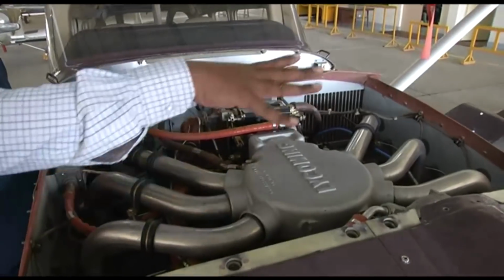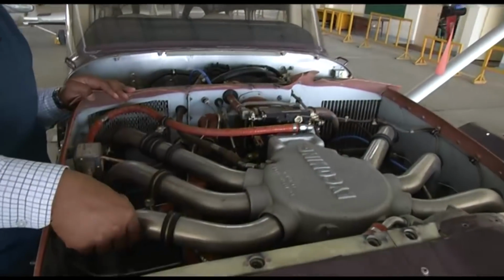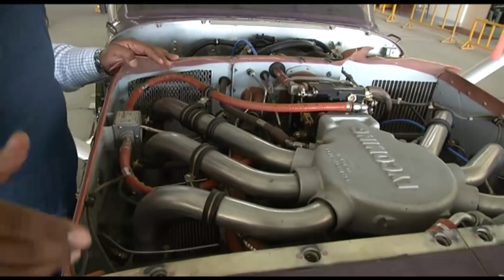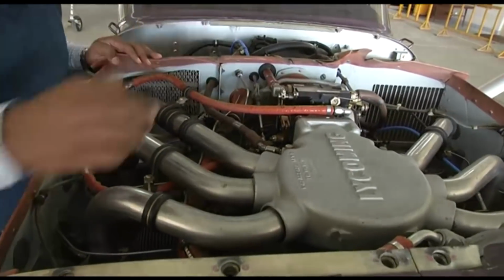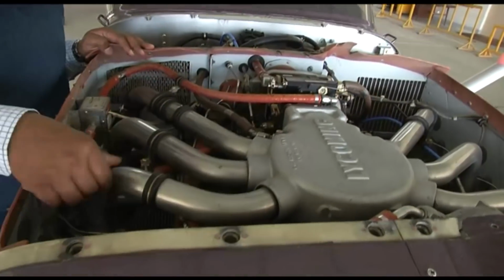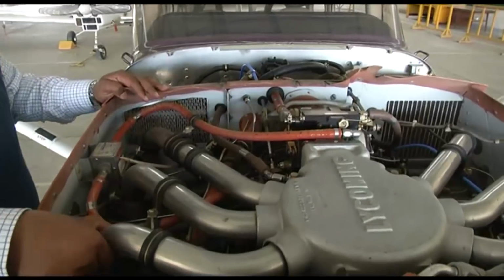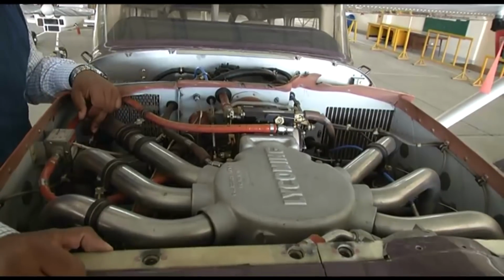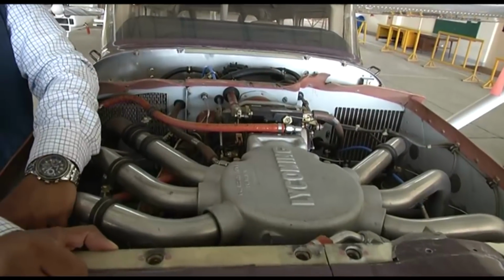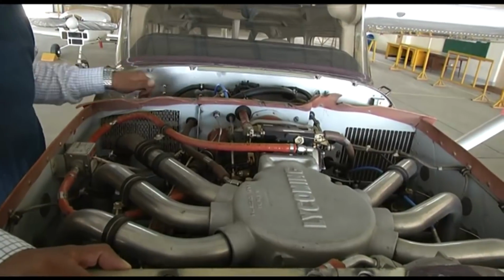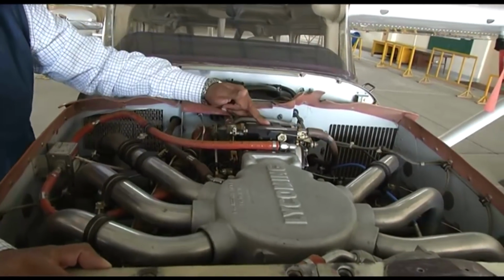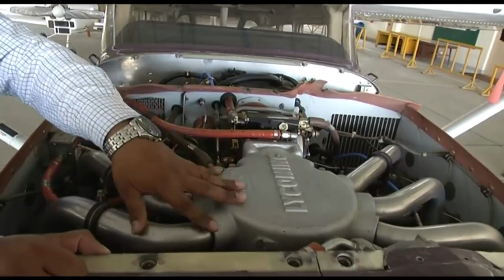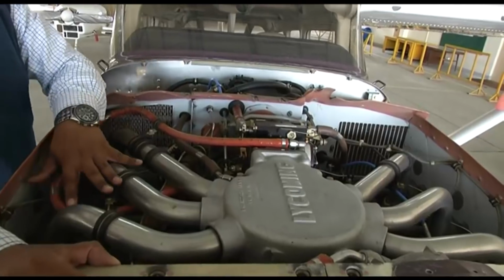You can see the manifold and the intake lines. You can see 3 lines on this side, since this is a 6-cylinder engine, 3 on the right side and 3 on the left side. So these lines are connected to the intake port of the cylinder. You see all the lines connected to the intake ports of the cylinder. So the air has entered through this ram inlet, gone through the filter, through the duct into the fuel air control unit. Then it comes to the induction manifold, and from the induction manifold it is ducted to the individual cylinders.